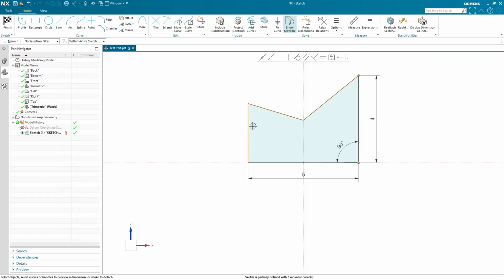And let's say we want this to be symmetric, like we want the other upright to also be 4 inches long. You can click on both and use the make equal constraint, and that will snap the length of this to be equal to the length of that. So you only need to define this one. If I go back and make this 3, it will shrink the other one at the same time because they're forced to be equal to each other.